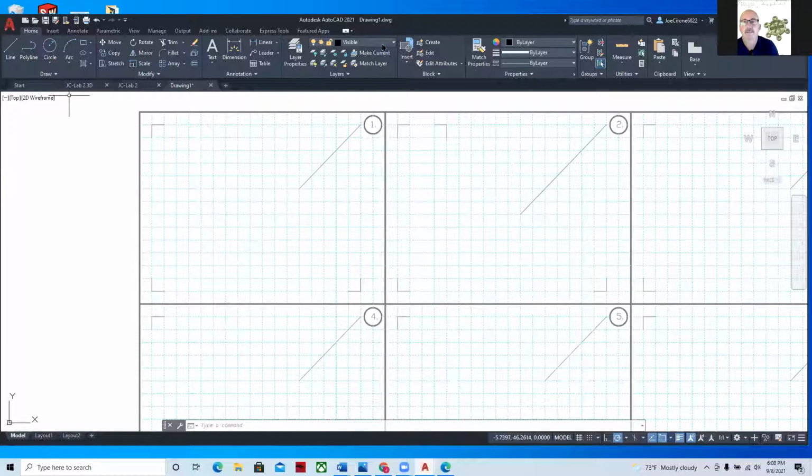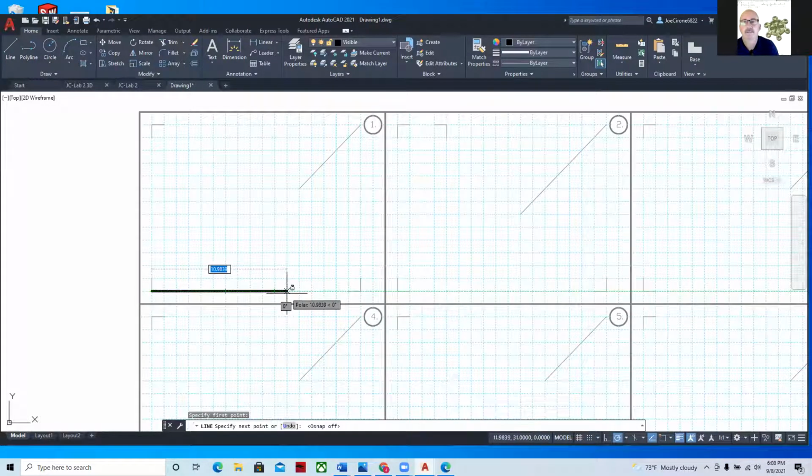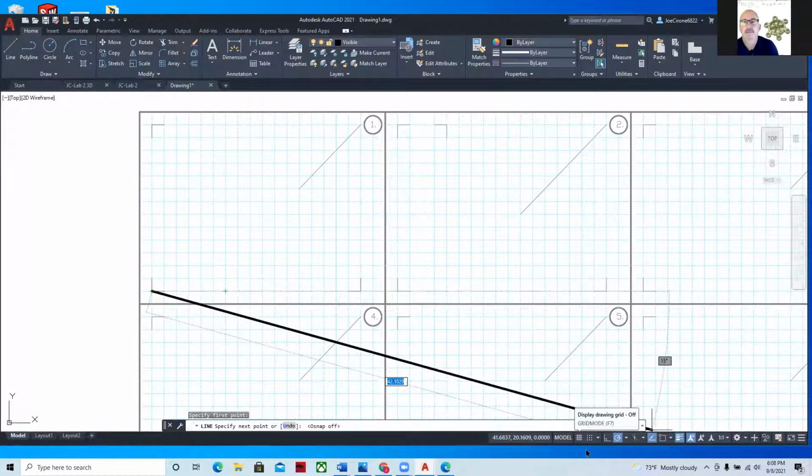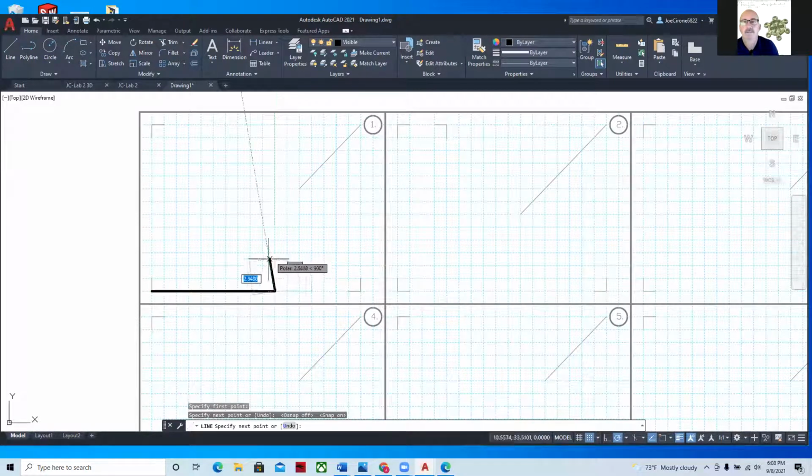and I were to draw it on the visible line layer, I would start off in this corner and then I would go 10 units over. And if you have the object snap on, that's fine. But if you have the O snap, that may get in the way. So we can turn off O snap and it'll work a little cleaner. And then we can go to 10 units. And maybe my object snap is not on. Let's see. It's not. There it goes.